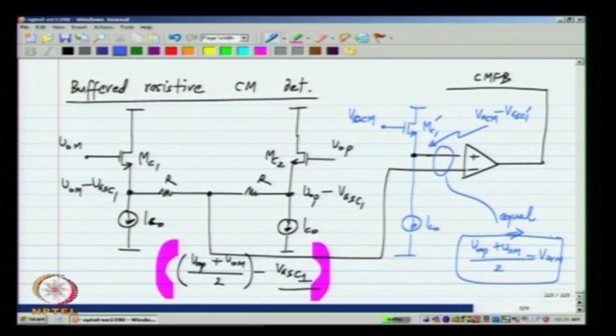Now, this business of exploiting matching on integrated circuits is very common. We have used it for simple circuits like current mirrors. There are so many cases where you have two things to match very well, you have to match all the parameters. In that case, you simply use a replica circuit. Now, that sounds vague, I have shown you one instance of it. So, whenever you have, let us say, voltage drops or some other parameters dependent on MOS transistor characteristics, you may be able to use a replica circuit, so that the dependence on MOS parameters, which is also process dependent, will be cancelled out.